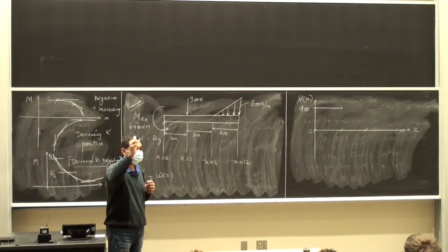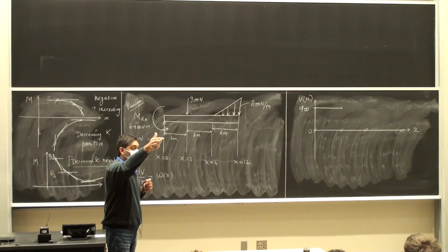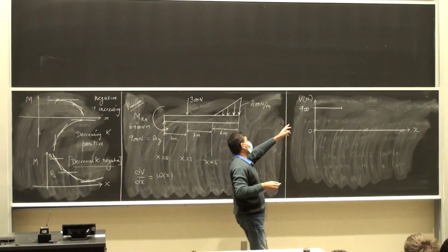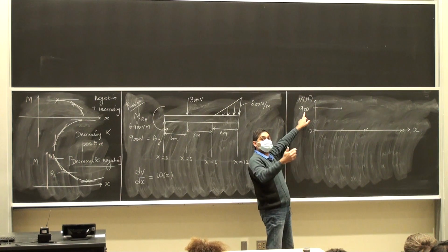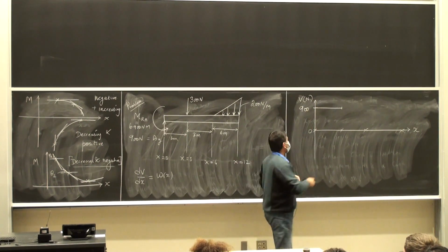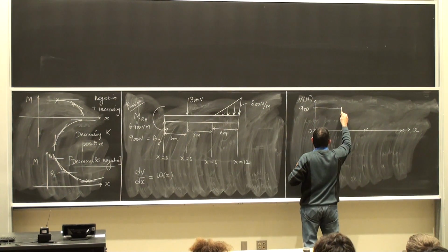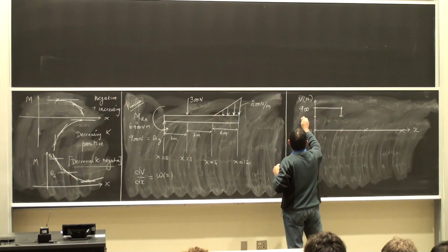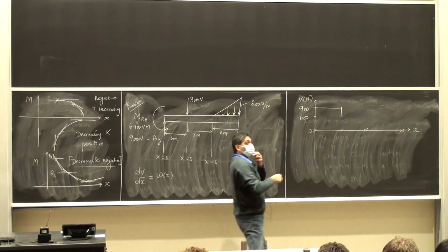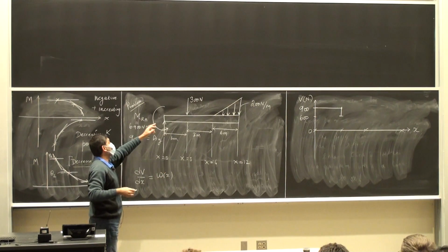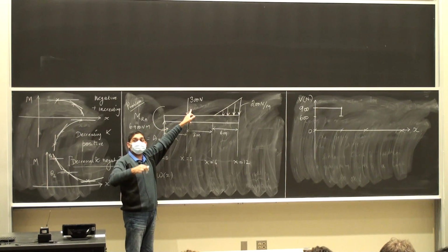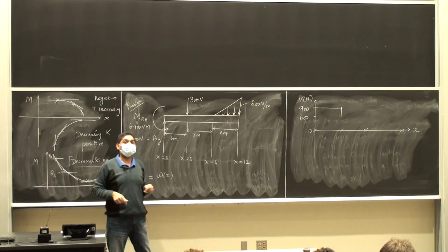Yes. You're going to drop down 300. Absolutely. Fantastic. I'm going to drop down 300 reduced from here. So I'm going to stop at 600 newtons. Why am I dropping down by 300? Is because I see that there is a concentrated force acting here. The force is directed down, and so it's pushing me down.